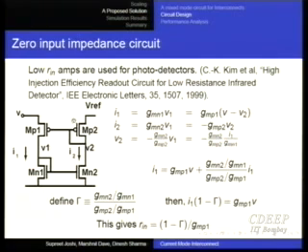Right? So what is I2? I2 is GMN2 times V2. Correct? That is I2. And it is also equal to, if you look at this, minus GMP2 times V2. Right? Because the V2 now will have a negative sign for the p-channel transistor. That same fluctuation. So while the current of one will increase due to variation in V2, the current of the other transistor will decrease at the same time.